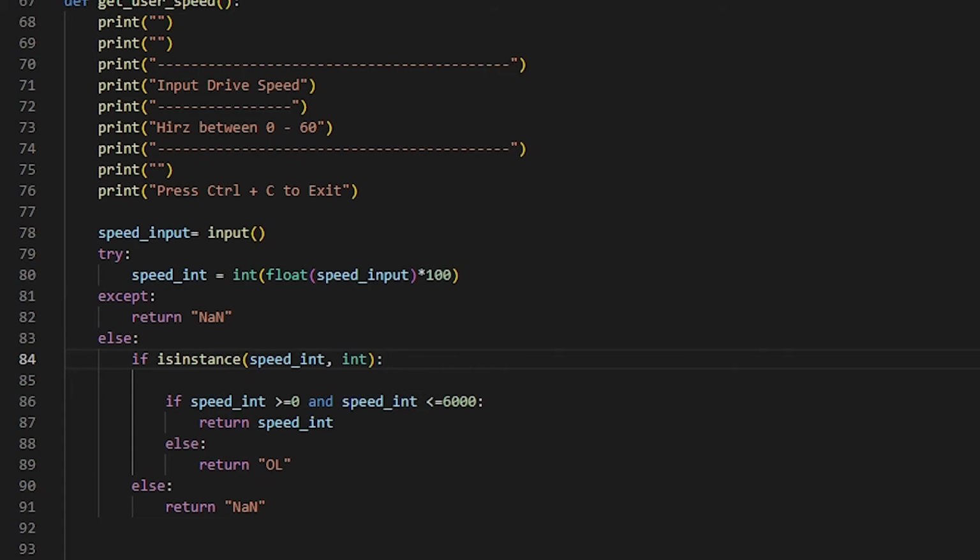So that's a nice little check you can do. If that is the case, we can move down here and we can do the final check of seeing if it's within the limits. This VFD is quite nice. If we put in 20,000 or whatever and send that off to the VFD, it wouldn't accept that, as it's out of its limits. The VFD itself wouldn't accept it, but it's always good to try and handle this in code and give out clean stuff to whatever you're doing, just be nice. And when you update equipment, just try not to put yourself in any nasty situations.